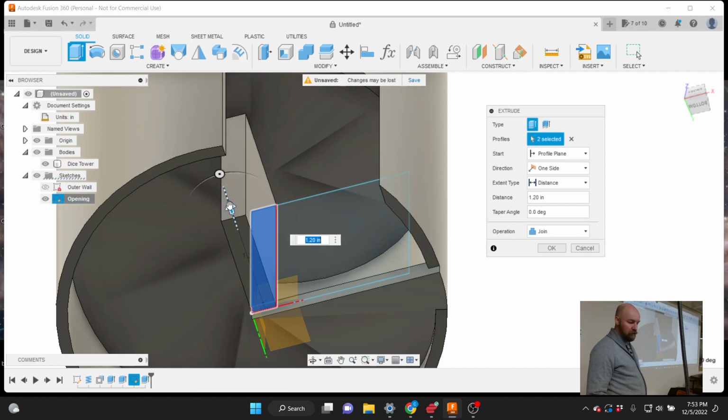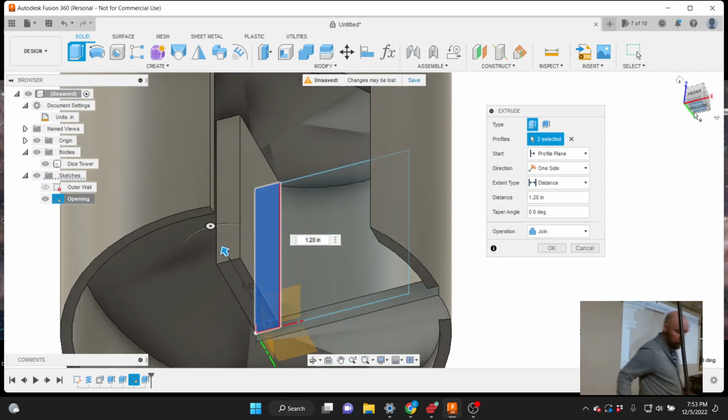Every time I try to extrude, I get a big circle. And I'm also, my textures are solid. So, yeah, click cancel. There you go. Now click create. Ah, here's what I see. Your outer wall sketch, if you turn that off. Your outer wall sketch was kind of like between the camera and the sketch that you wanted to click on. So it wasn't gonna let you click on it because there was something in between. I feel like I must have missed a part of it. Oh no, you're good. Yep. There you go. Perfect. Got it.